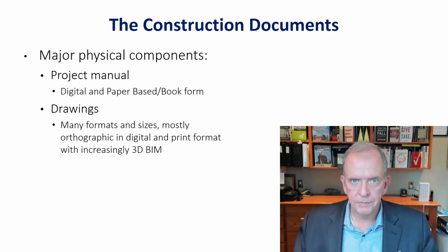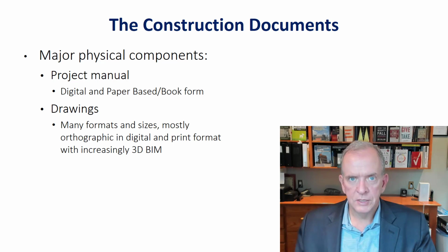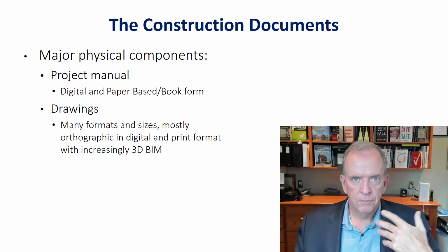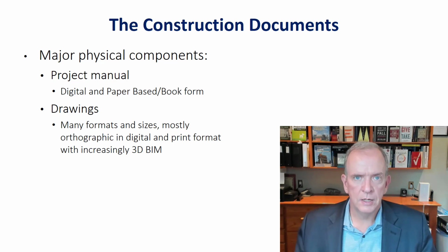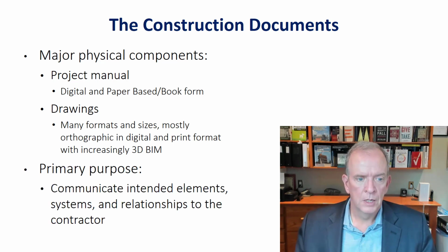We call them scope gaps, where we've missed things, and they come back to haunt us later on in the project because maybe we didn't include it in our estimate, our budget. Maybe we didn't schedule the time in for this work. Maybe we're asking subcontractors to do things that they weren't expecting to do. There are all of these problems that fall out from not fully knowing and understanding the construction documents.